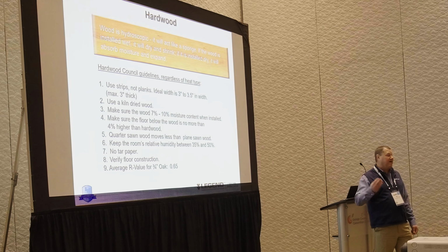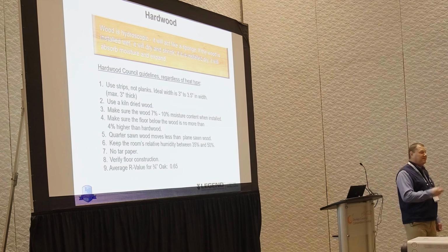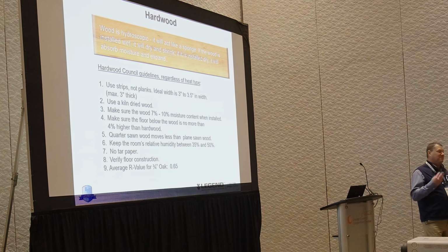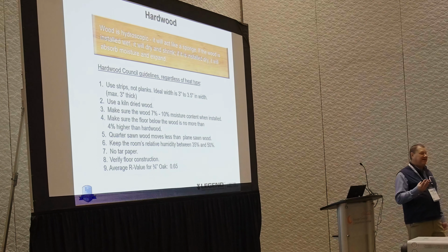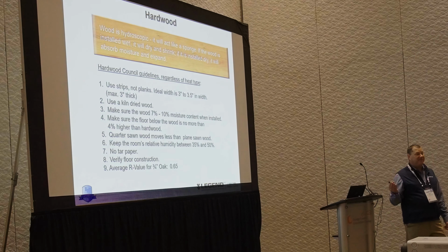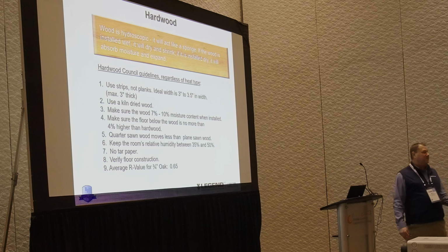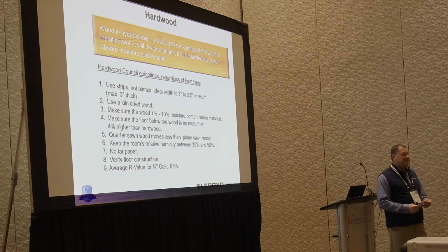Some of them are 85, most of them are, but if you get a manufacturer that says the maximum water or surface temperature I want is 80, and we design it to 85, and something goes wrong with that floor, as an installer, you're going to be in trouble. The designer's probably going to be in trouble. The wholesaler's going to be in trouble. Your cousin Vinny that told you about the project, he's probably in trouble.